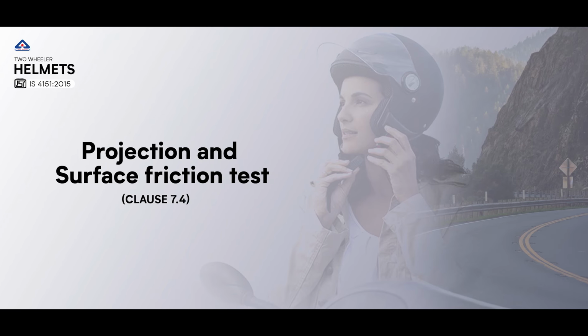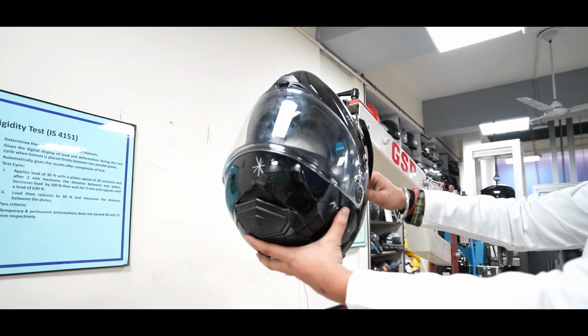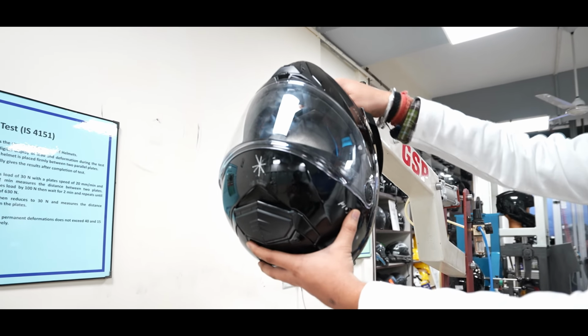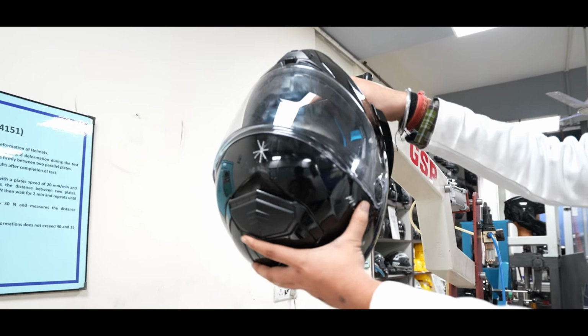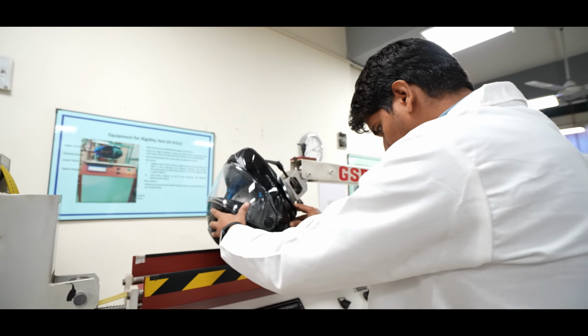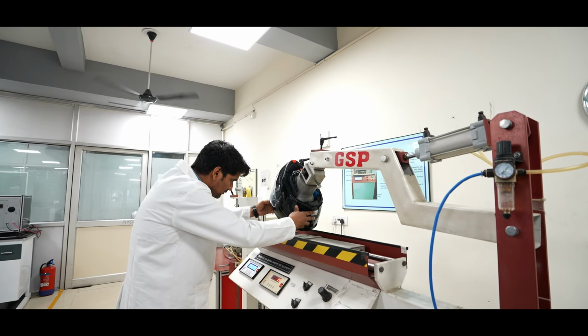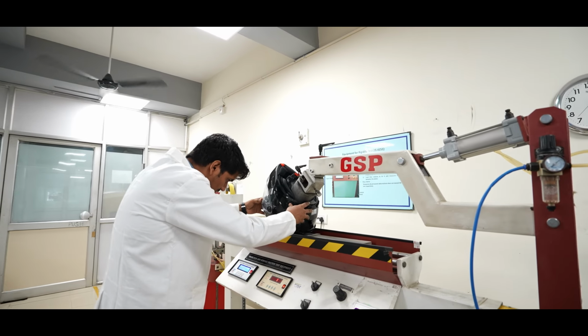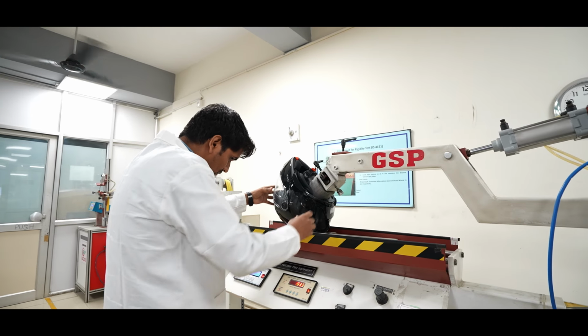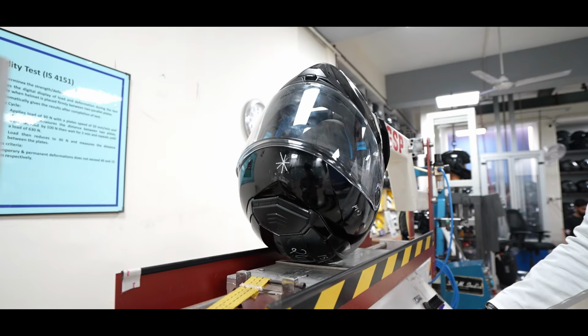Projection and surface friction test, Clause 7.4. In the projection and surface friction test, the helmet should not be brought to rest due to projections on the helmet, and the helmet should slide freely on the carriage and over the disc under 40 kg loading at a specific speed. The surface friction test ensures that the helmet remains stable on the rider's head during a sliding or impact.